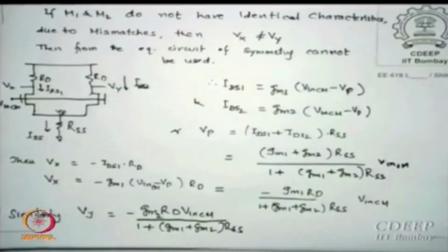What is the gain we are now looking for? That is what is called conversion of common mode into difference mode, because we are going to get a difference signal, Vx minus Vy, with reference to what? Vin,CM. So the gain of more relevance is not just the way I showed you earlier, it is essentially Vx minus Vy divided by Vin,CM, which many times is called AVCM dash. Have you written it down? Then I can show you the next slide.